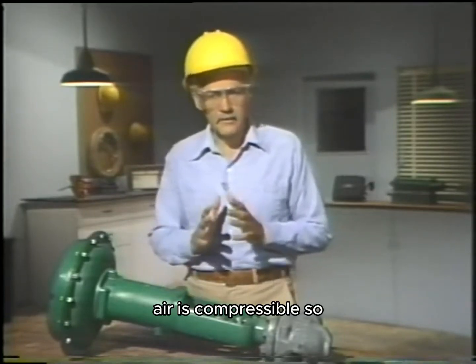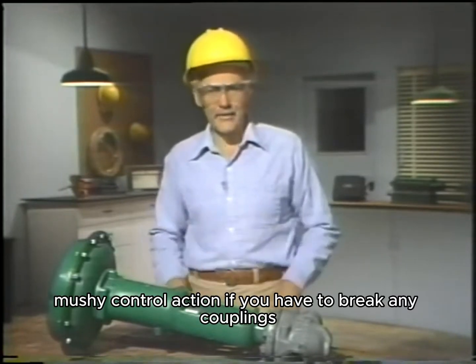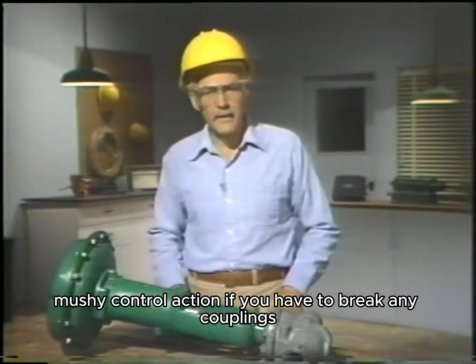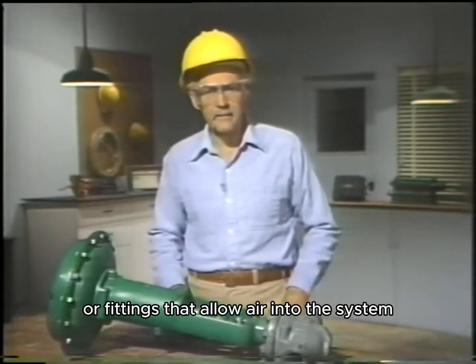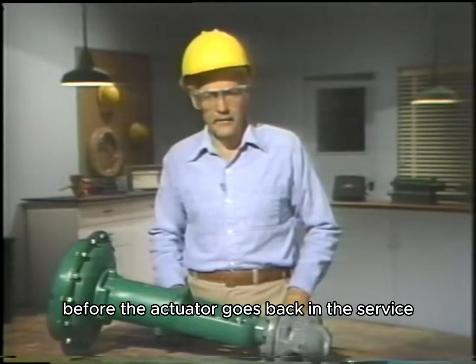Air is compressible, so any air in a hydraulic cylinder will result in mushy control action. If you have to break any couplings or fittings that allow air into the system, the air must be completely bled off before the actuator goes back into service.